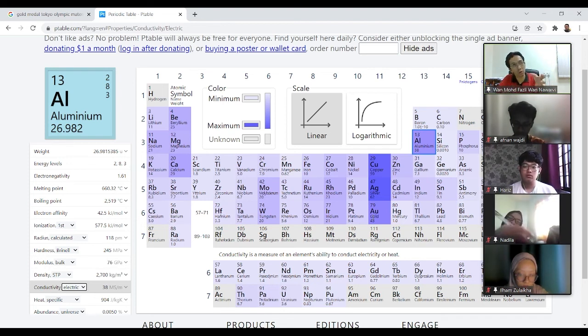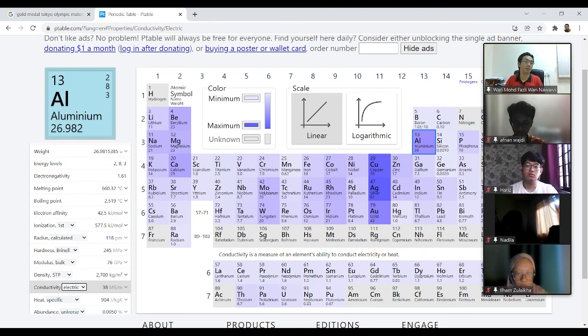So that's why they use gold in this thing as a conductive element, because it's not oxidized, and then the conductivity is not hindered lah. It does not go down lah. It's maintained like that. So even though the gold, the aurum here, is more expensive than copper, and even though gold has lower electric conductivity compared to copper, they still use gold because copper can oxidize.